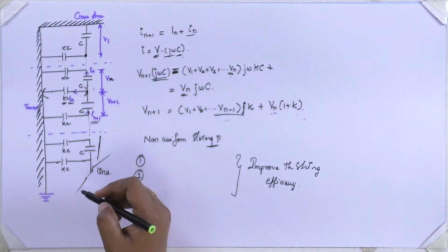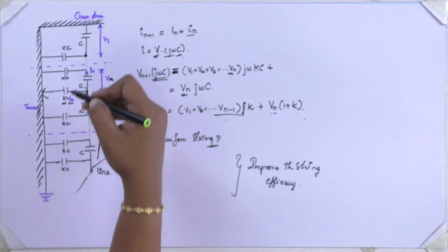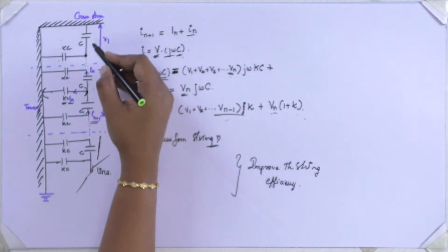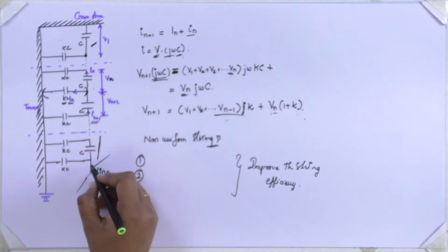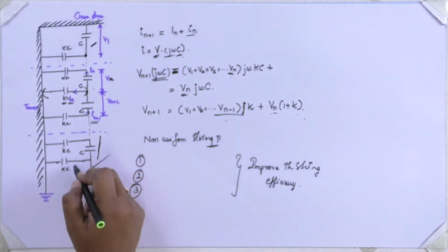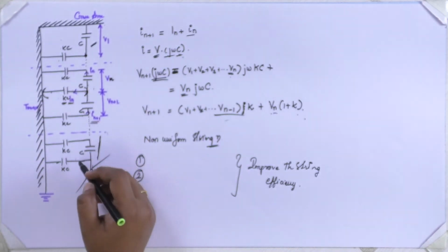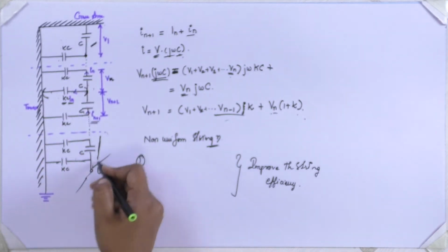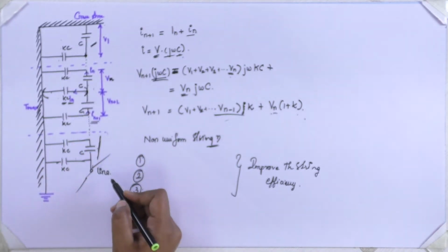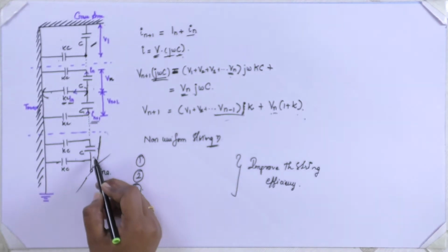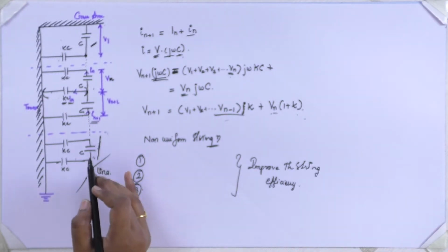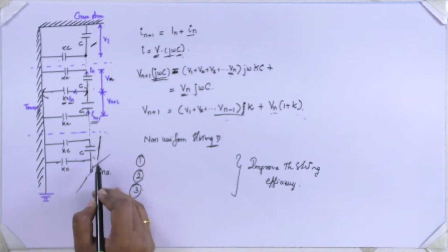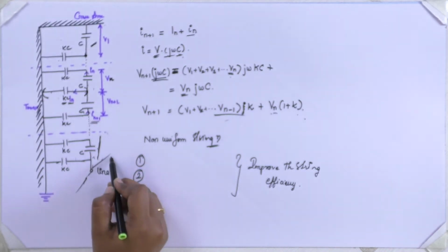So here I have to put maximum insulation, near the cross arm. Understood? Because the stress will be at the maximum point here when compared to the upper region, because the transmission line voltage is nearer to this point. So at this point only the maximum stress will be there. But practically, what we are thinking of is reducing the stress between the line.